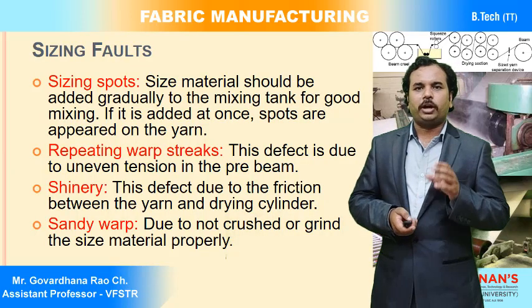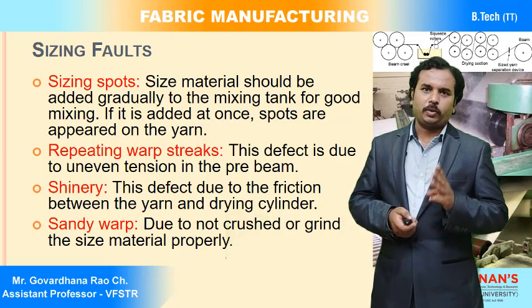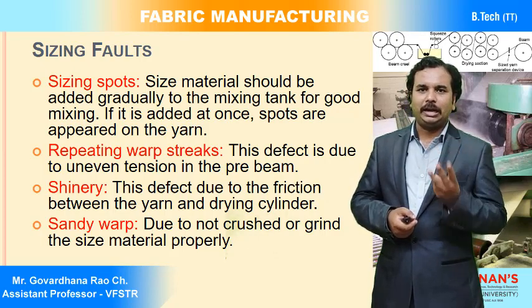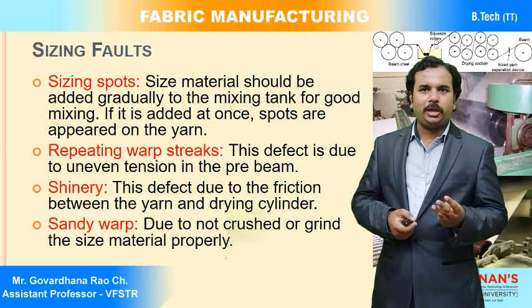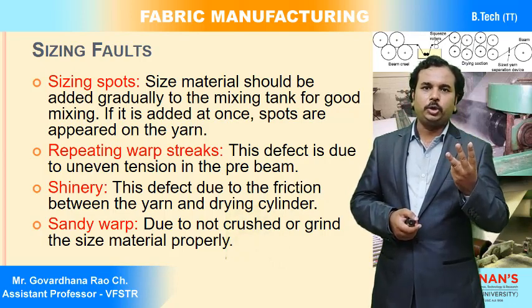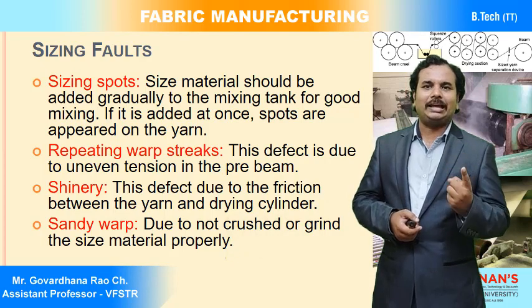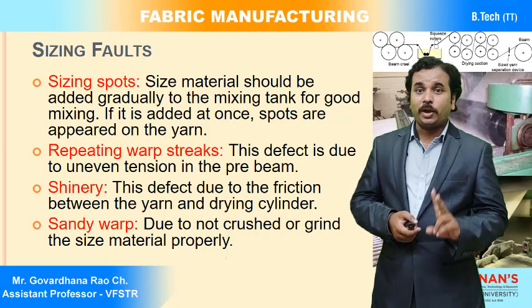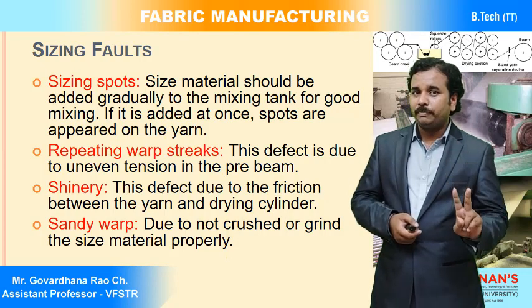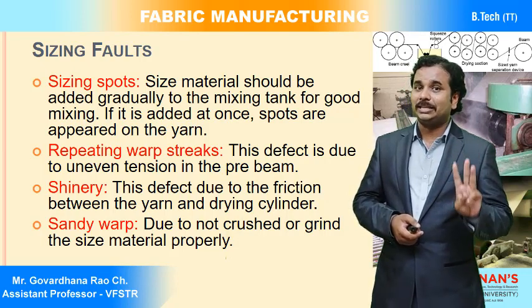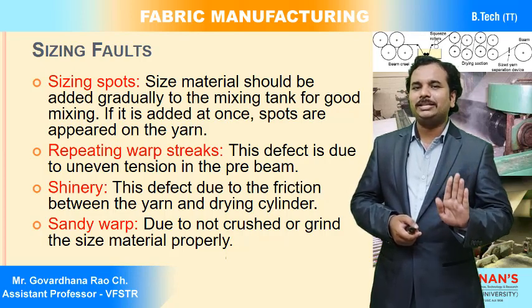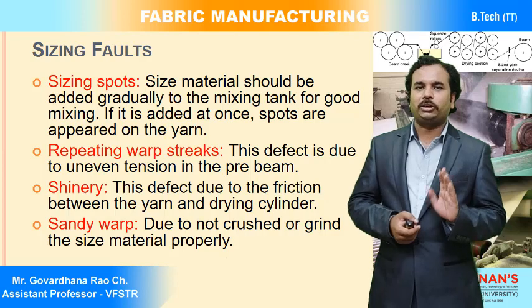So what are the three methods of drying? Conduction method, convection method and radiation method. Most popularly, for bulk orders and MNC companies, we prefer and use the conduction method of drying. That is why we discussed the 2-cylinder sizing machine and multi-cylinder sizing machine. If we are using cylinders, it is a conduction method of drying.